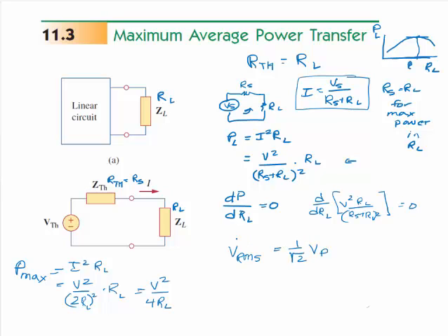This is the thing that you measure. VRMS is what you measure with your power meter, and VRMS is also what you have to use when you do power calculations. Otherwise you have to pay attention to the 1/2 and things like that for averages.